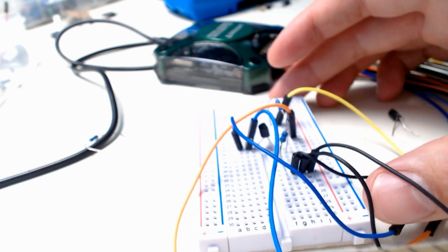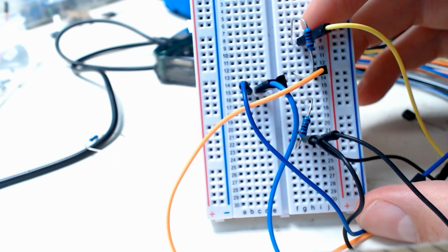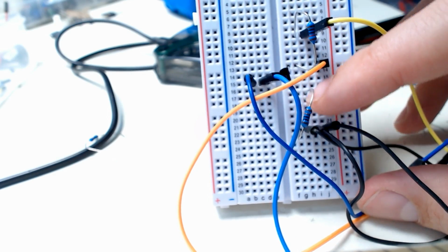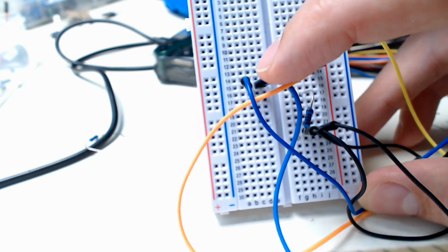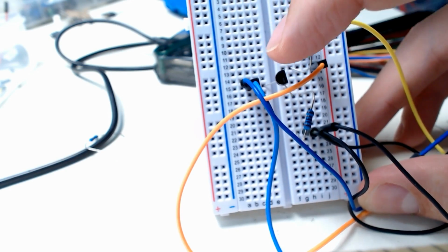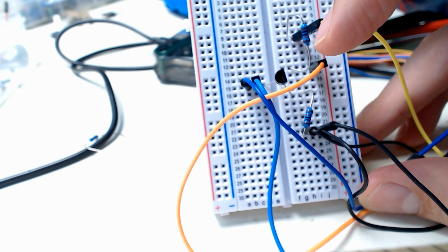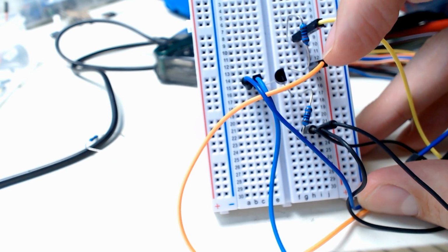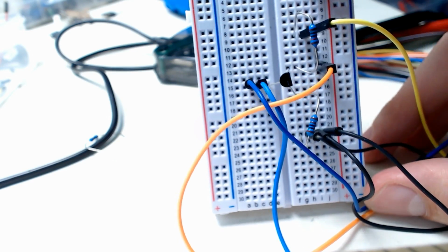Sorry. So, a simple transistor here, right? Up here, we're feeding the signal in down through a collector resistor. There's an NPN transistor there, the 2N3904, and then there's an emitter resistor, and then we're also feeding in a signal over here on the base. We're also monitoring that signal. This is channel 1 here and channel 2 here. And so what we'll do is go and look at this on the quote-unquote scope screen and see how